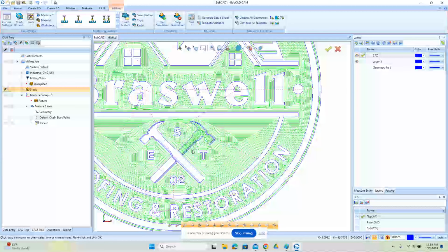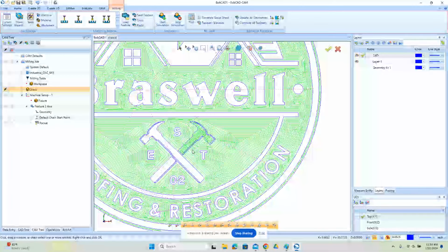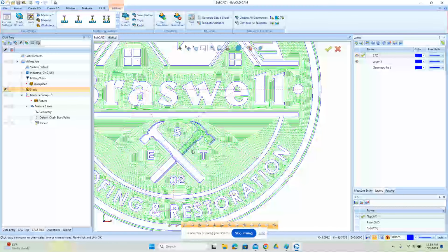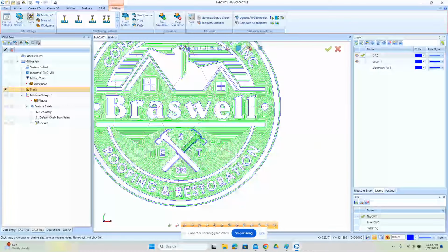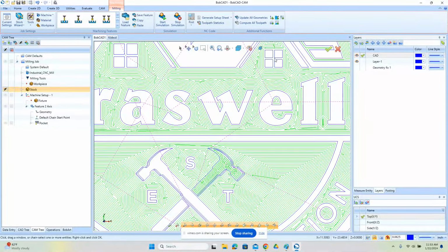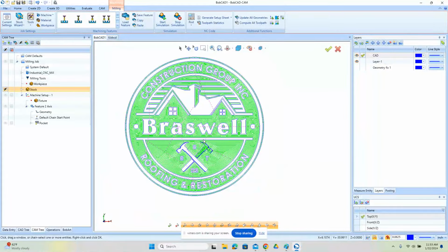But when we're talking about making a part versus designing a part, it's a good idea that both the designer or the artist and the person that's doing the manufacturing or the programming work together and know about some scenarios. We're cutting with a round tool, so all our corners are going to be round. The size of gaps between, like you can see in these windows here, is too small, so the tool doesn't fit. The tool's only going to go where it's going to fit.